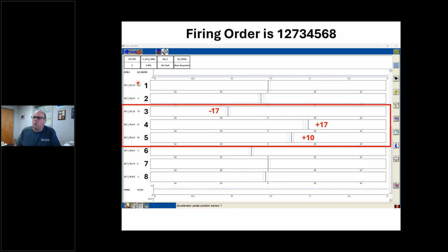That one's 1, 2's 3. They're pretty much single digits. A lot of techs will look at this and say, oh dude, you got 3 bad injectors. So they go to the service manager and say, this truck needs a set of injectors. Look at this, he's got 3 in the junk. It's got 222,000 miles on it. It's whooped out, it's chipped up, it's the whole smash.